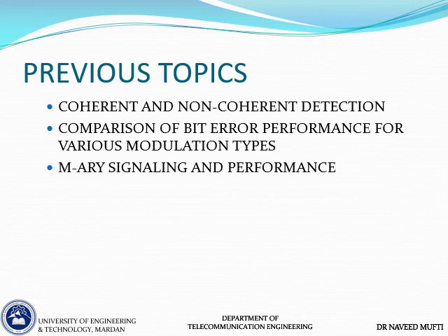So we looked at coherent and non-coherent detection to differentiate between them. Obviously, one of them requires extracting the incoming signal's phase so that it is able to generate a local oscillator of the same phase and frequency at the receiver. That is coherent detection. Whereas in non-coherent detection, there is no such requirement. Coherent detection is obviously better in terms of its noise performance, and non-coherent detection is obviously better in terms of its simplicity of hardware. So that's what we discussed last time.